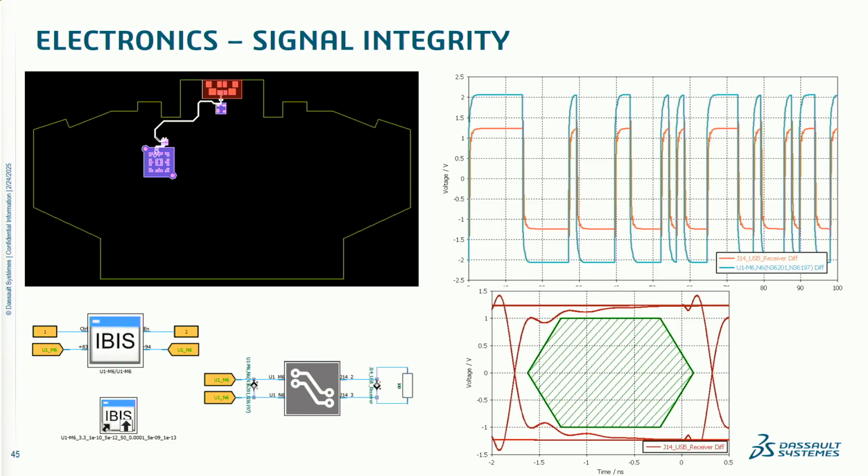They're basically telling us what data, what series of zeros and ones, at what intervals are coming out of that chip. Now, when we look at that blue and orange graph in the top right, the blue one is our transmitted signal. The orange one is our received signal. So there's obviously some voltage drop as we go along, but it's not just voltage drop we're looking at. Ultimately, what we're looking at is something called an eye diagram.